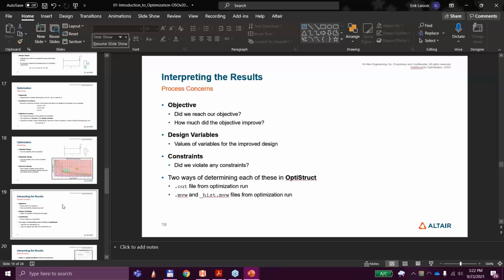But if it turns out that I'm going to remove 3 pounds out of the mass of the control arm, and over time that means that I'm going to get better fuel efficiency with my vehicle, I can create the part cheaper, then heck yeah, it's worth the change.